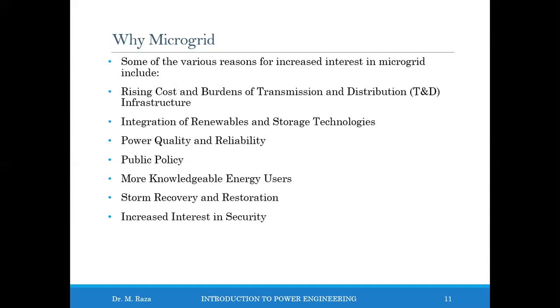When the main grid loses power, the microgrid can switch to island mode. As long as there is an adequate source of power at the local level, for example, diesel generator, wind turbine, fuel cell, and photovoltaic, etc., the power continues to flow while the rest of the community is enveloped in darkness.